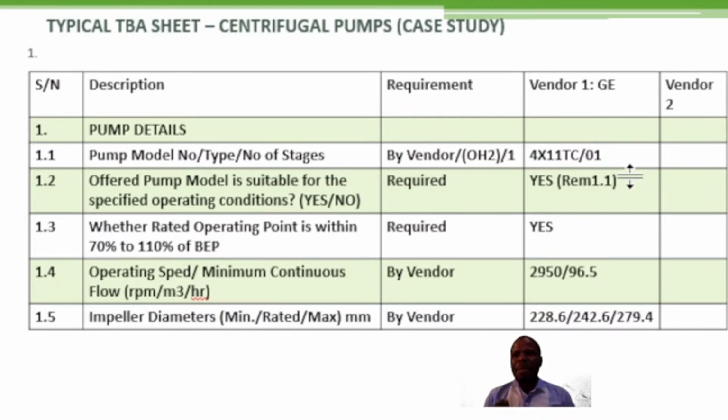All right, the mechanical as well as the hydraulic performance, including NPSH for the complete range of operation of the offered model, shall have been established in the shop test. So the offered pump model shall meet the minimum service and manufacturing experience specified.